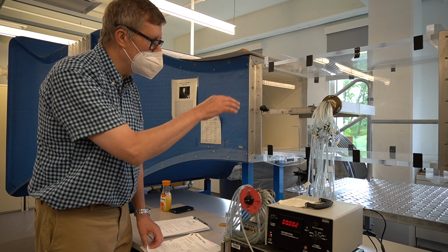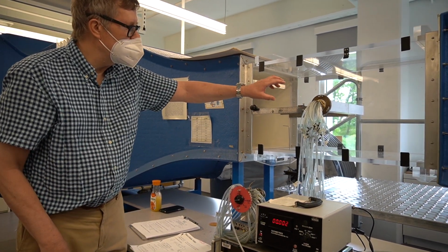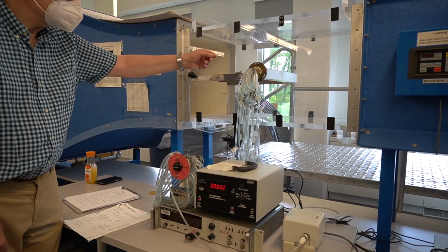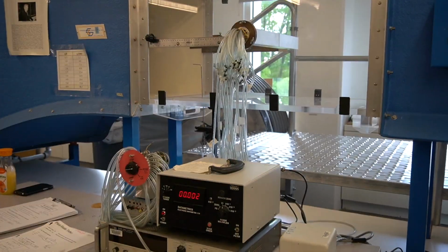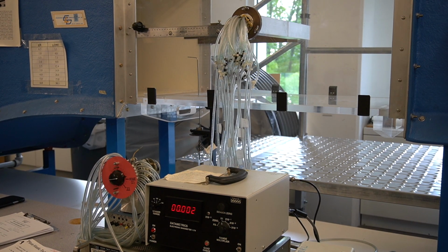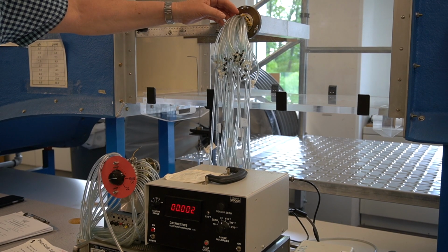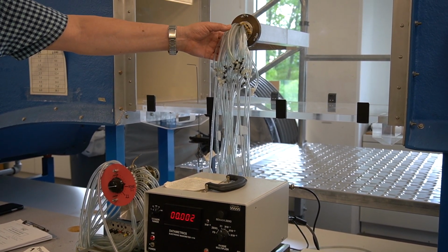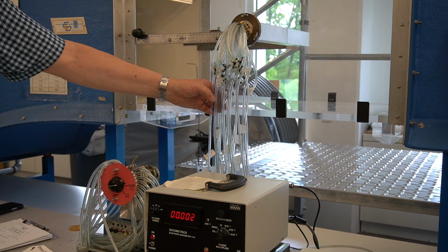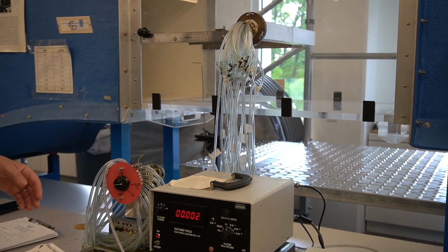Let me show you where the pressure taps go to. So they're on the front face and the rear face of the cylinder, halfway along the span. And then the little pressure taps are attached to, what's it called, hypodermic tube. And these are all attached to Tygon tubes as they come out from the cylinder at this point where my hand is. So all these, look at this stuff. You get something wrong. We had somebody who got this wrong. They spent 10 years trying to sort it out. But basically those tubes come down here.